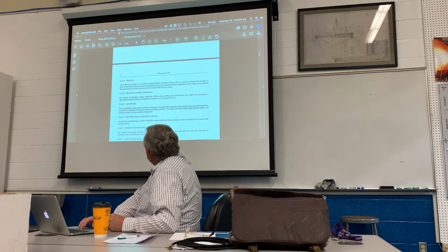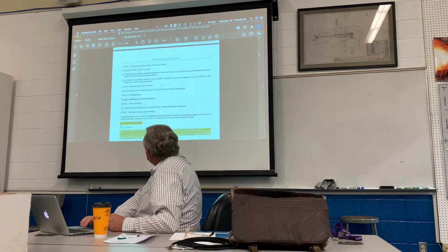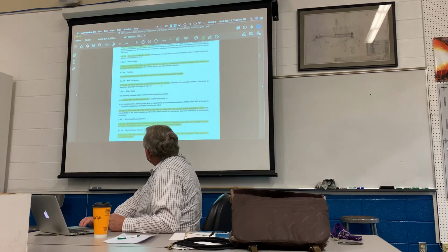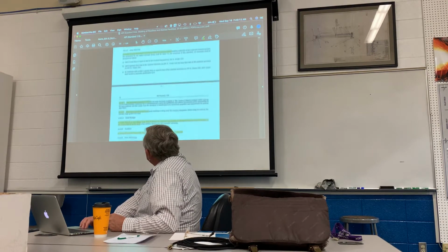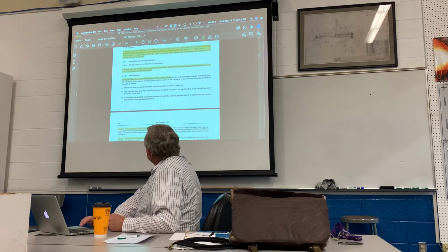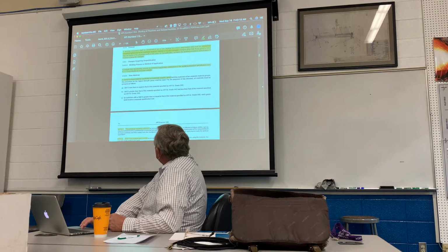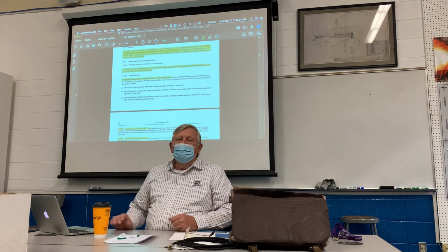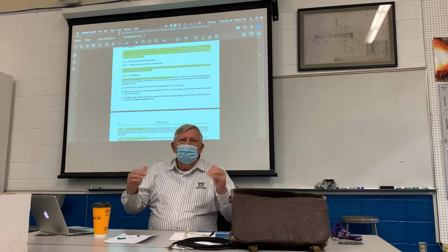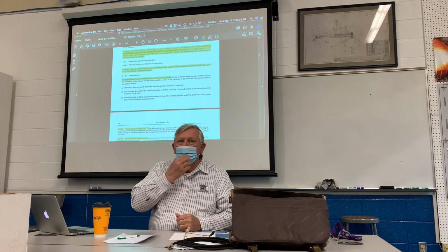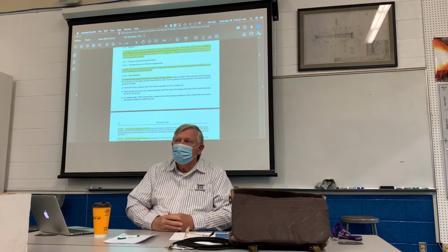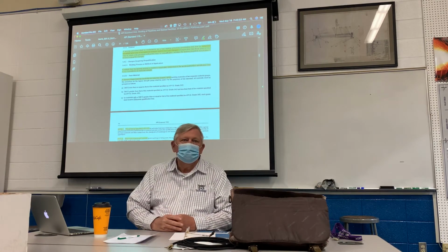So if you go down to 5.4.2.2, right there, base materials, you have 3 groupings: less than X42, 42 to 65, and greater than 65. So what are those grades? You might have to Google that. But you could pick one of those that are listed there.